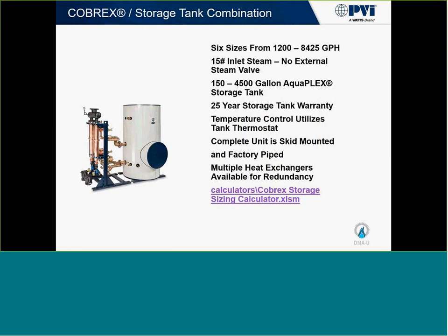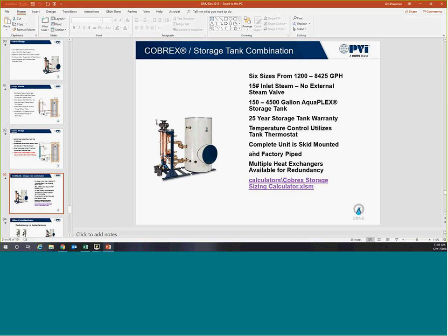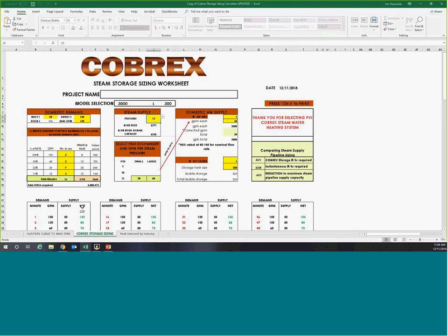So, like we said previously in a few slides, what we're able to do is go to a sizing chart. And I want to show you this really quickly. Basically, what you can do is look at your system demand in 15-minute increments. So we're looking at quarter-hour increments because you're not going to be flowing 100% for all 60 minutes out of the hour. And so we have different variables that you can throw in here, your inlet temperatures. So let's go worst-case scenario. We're looking at 40 degree. We want our outlet to be 140. We want our max GPM to be 120. So based on that